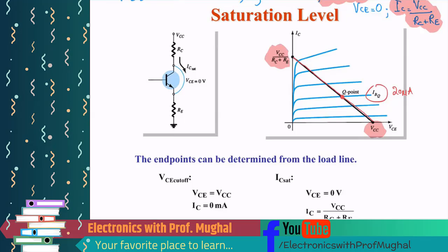Okay. Now, again, you have much more flexibility this time to change your Q point. So say if you want to move your Q point to over here, what are you going to do in terms of VCC or RC plus RE? What you could do, say I want to keep VCC constant, I can change my RC plus RE. So the sum of it, do you need to decrease it or increase it in order for me to get the Q point over here? Increase it.